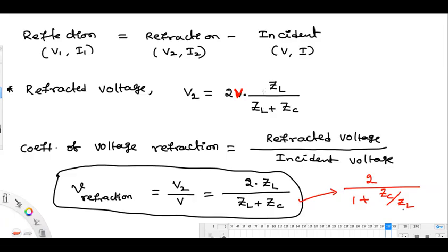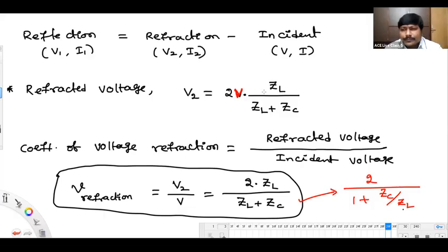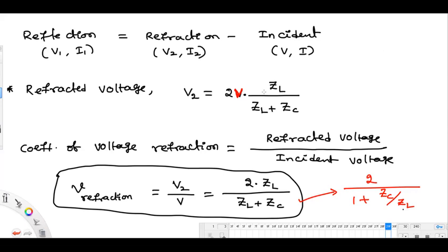Here, half CV squared, that energy stored in the transmission line will be valid for all the time. For fast calculation, you have calculated V equals I into ZC for starting. Then after that, we are calculating by seeing the transmission line conditions, not by energy.